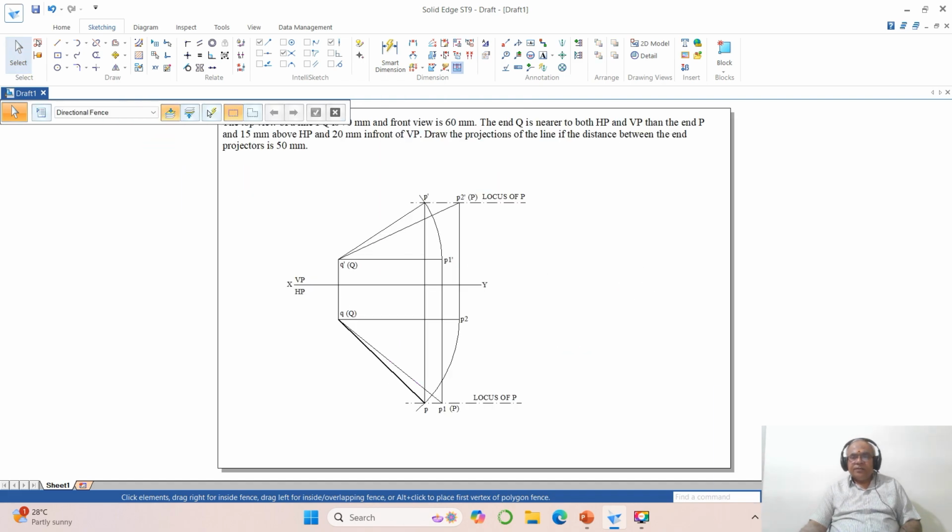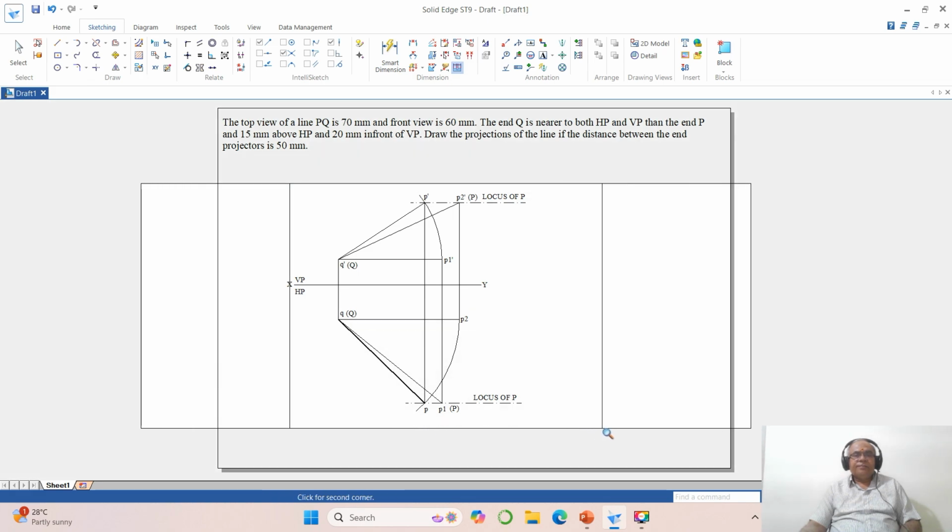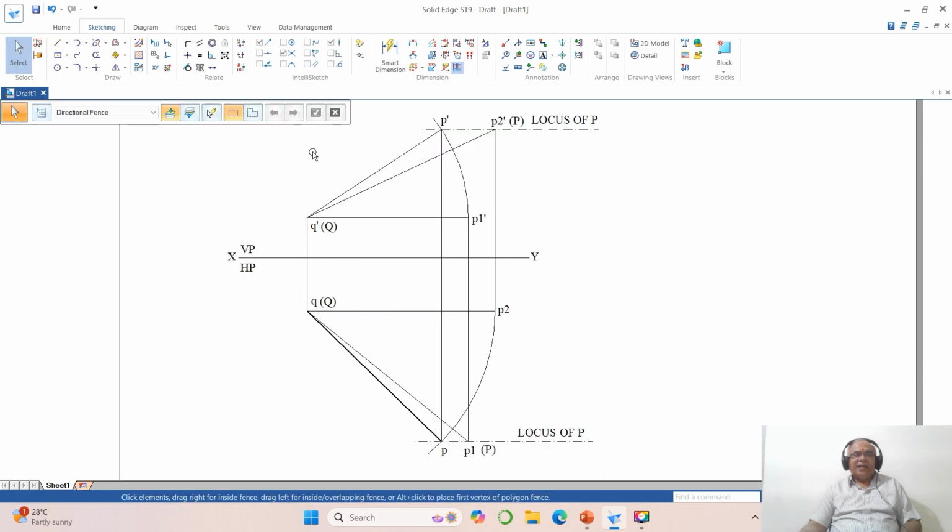Similarly, go to fit, come down to the front view. Now select this line, make this line 0.5, and similarly make this line 0.35. Once you do that, now we want to go for the dimensioning. After doing all these things, only then go for dimensioning. Take this line, make this 0.13 because it is the XY line.